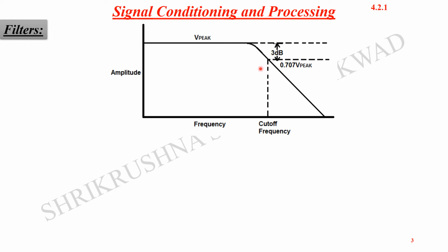Okay, so this cutoff frequency is called the higher cutoff frequency, because we are dealing with the low pass filter, because low frequencies are allowed and high frequencies are stopped. So beyond this point, 1 by root 2 times the maximum amplitude, because we are dealing with the RMS value, we can have 1 by root 2 times the maximum gain or amplitude.